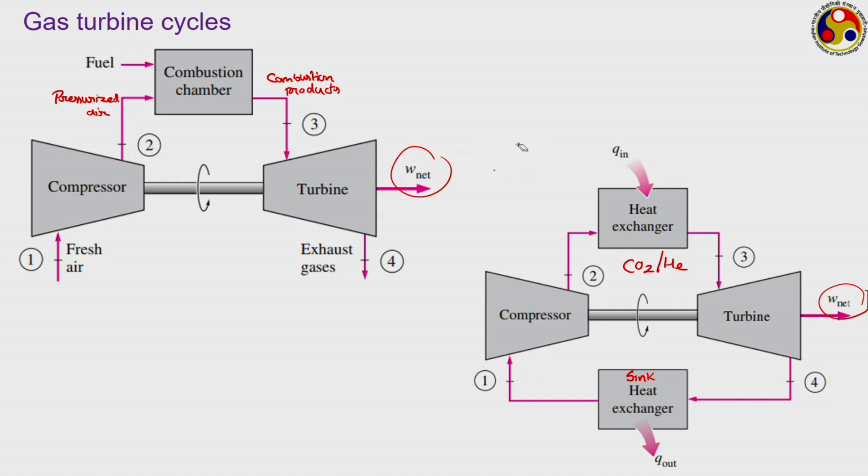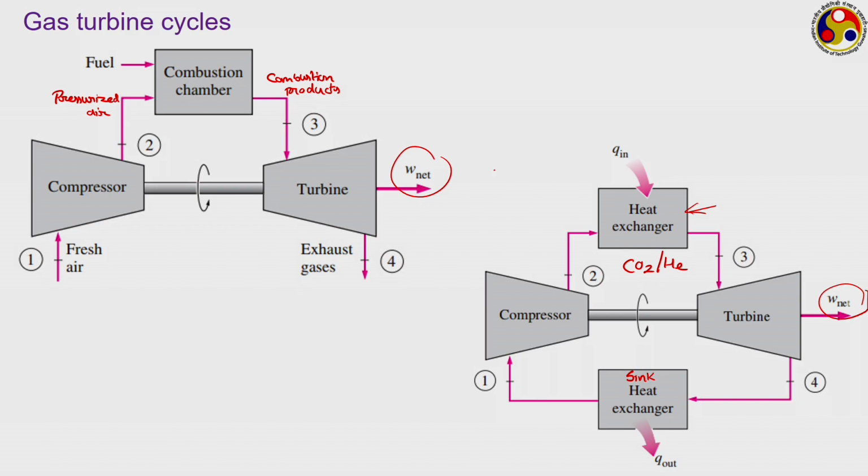So, your open cycle gas turbine is an internal combustion device, where you have a combustor present and combustion gases are used as the working medium in the turbine, whereas in case of a closed cycle gas turbine, we do not have a combustor; rather, we are using a second medium which is receiving the combustion heat, or heat released during combustion, in this heat exchanger. But what is common then in between? The common is the three parts.